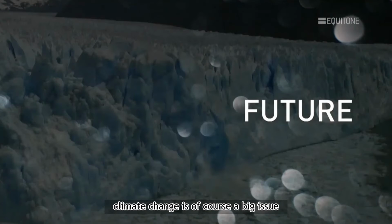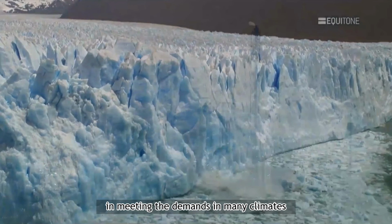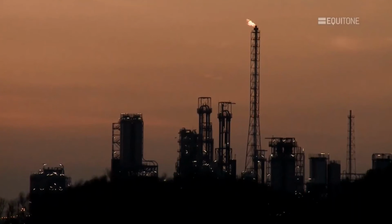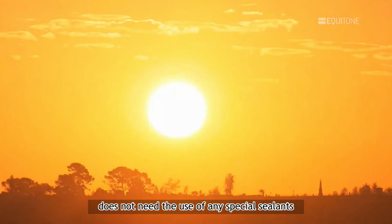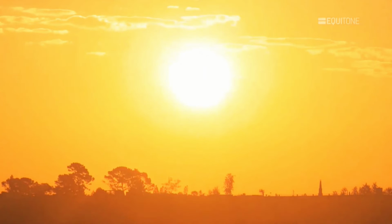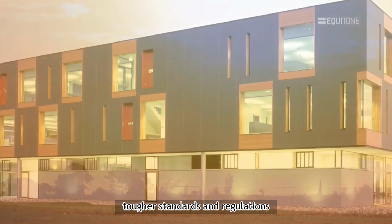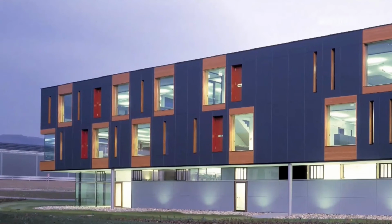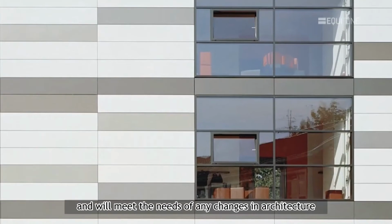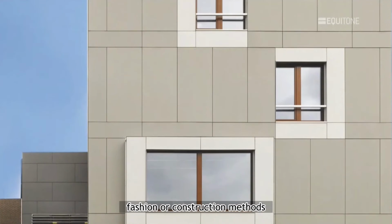Climate change is of course a big issue. As you have just seen, rain screen is most suitable in meeting the demands in many climates. The drained and ventilated rain screen that we promote does not need the use of any special sealants and relies on simple techniques to work. Tougher standards and regulations can easily be met with rain screen. Rain screen is adaptable and will meet the needs of any changes in architecture, fashion or construction methods.